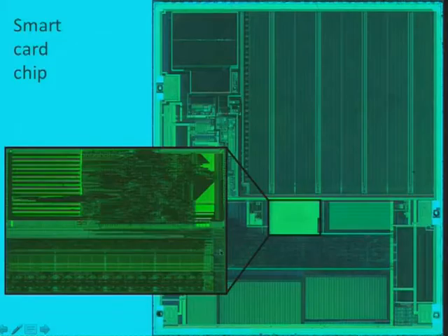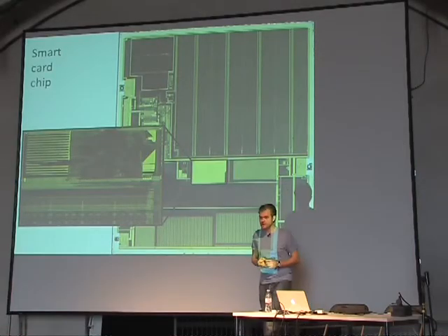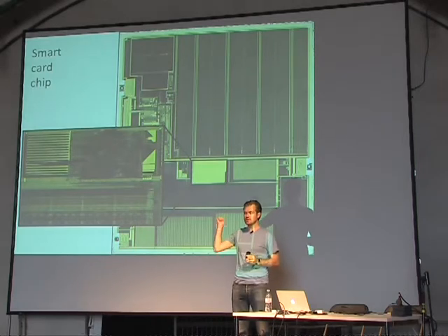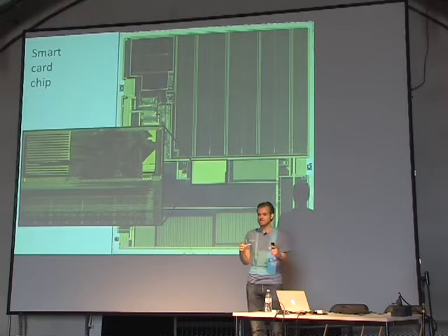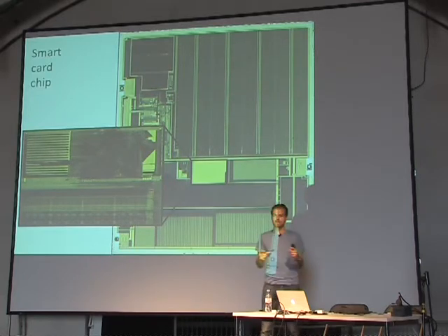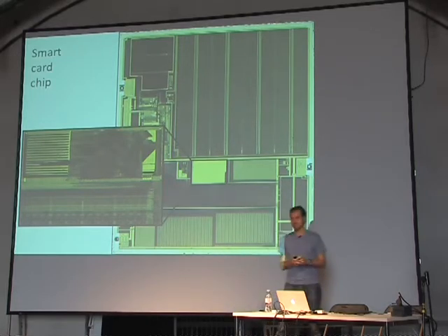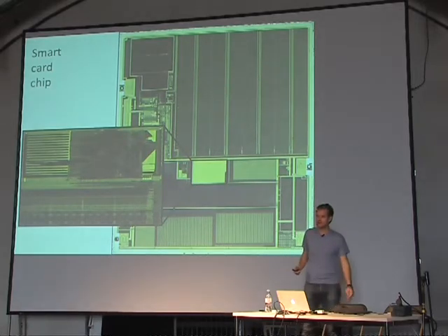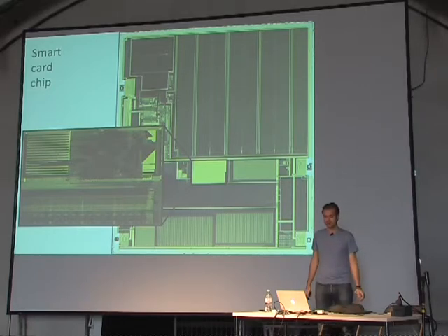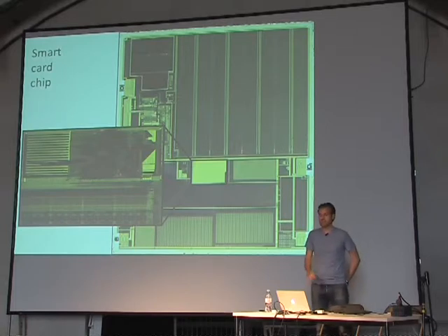And this chip, for instance, interestingly enough, the one with the memory encryption function that we've been reverse engineering and presenting today, comes in all kinds of different feature sizes. So this exact footprint of a memory encryption function has been found in smart cards for 10 years. You find this all the way from 600 nanometers down to like 210 nanometers, right? And you basically get to choose your target for reverse engineering. Just take the one with the easiest imaging method, and the results apply everywhere.